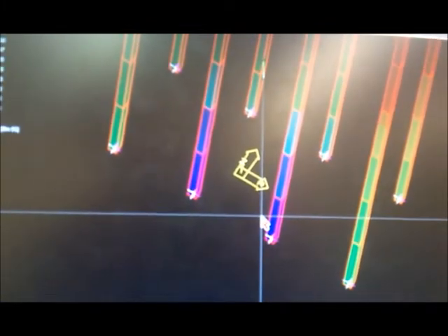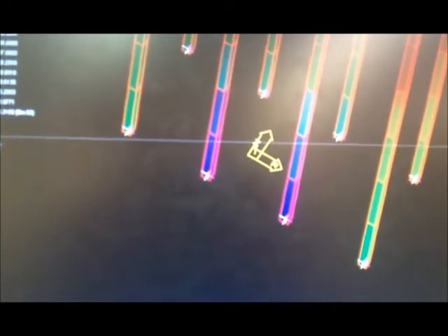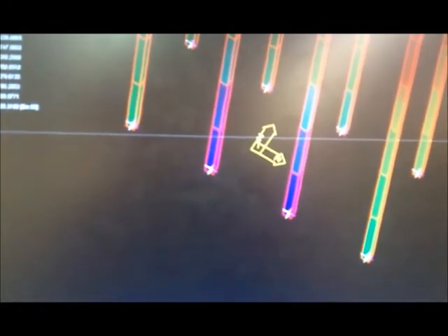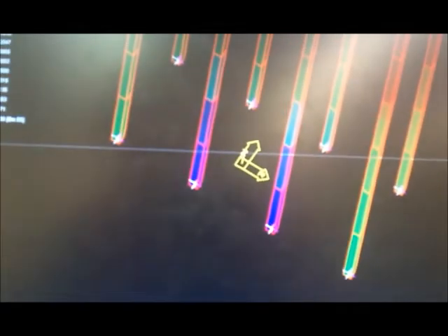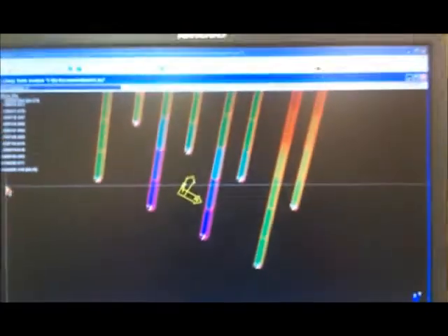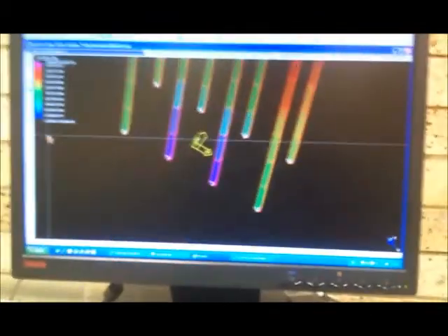What is the stress value of these columns? 1, 2, 3. It's 12.5 megapascal. Is that okay? Yeah. We have capacity up till 32. So this is 12.5, so that's absolutely okay.